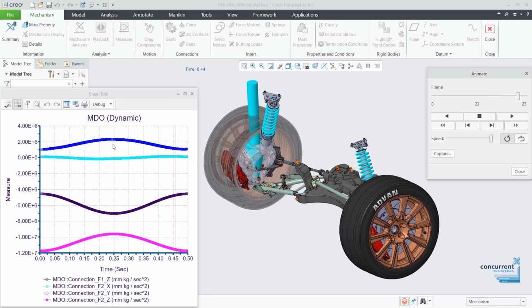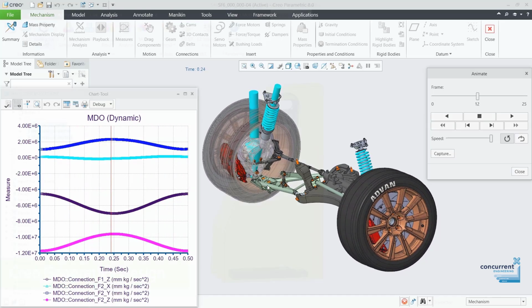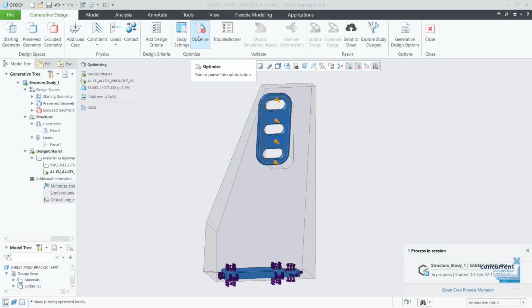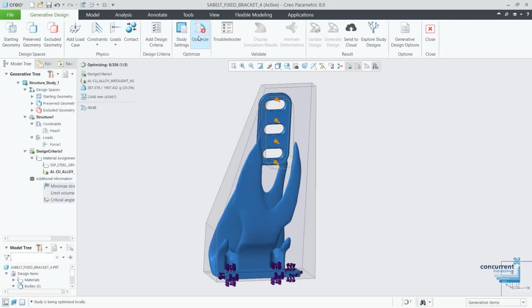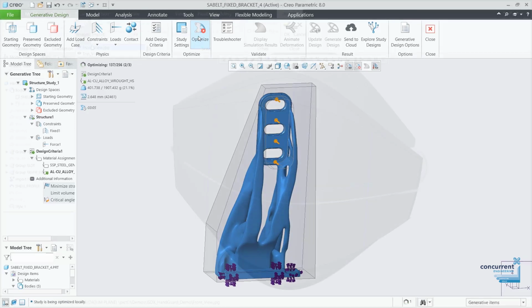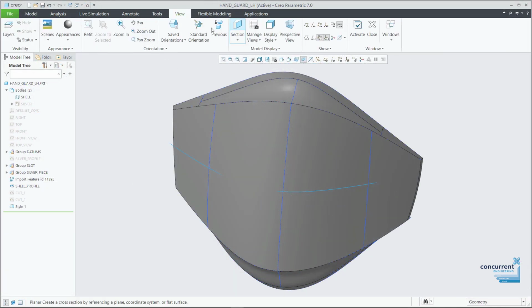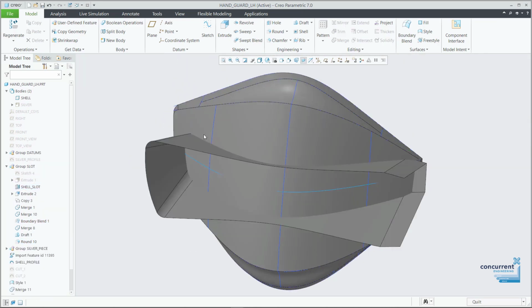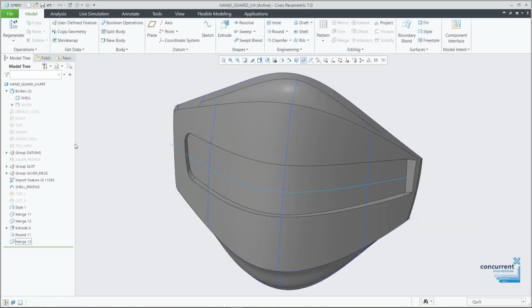Now, there are a number of different levels of control you can have here, and this often depends on whether you are a lone worker or part of a larger organisation with an established plan. In the background of Creo, indeed when it starts up each time, it reads a file called config.pro. This is a configuration file for your version of Creo, and essentially it's simply a text file with a list of options for different aspects of the software.